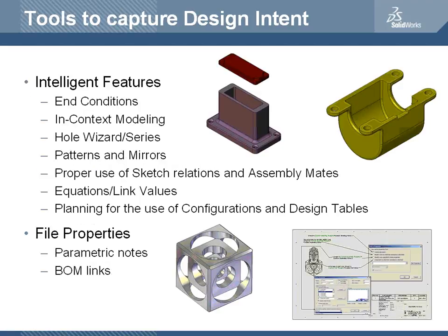Now we'll talk about tools that allow us to capture our design intent. Intelligent features such as end conditions. We have more than just a blind for our extrusions. We also have the ability to do some in-context modeling. We'll talk about the Hole Wizard, Hole Series.